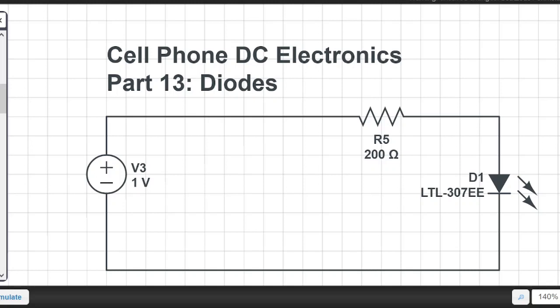So the diode makes sure that if you have something like an inductor in your circuit, and the magnetic field that the inductor creates collapses, and the current has to go back into the circuit, where does that current flow? Does it flow towards the diode? No, it can't.